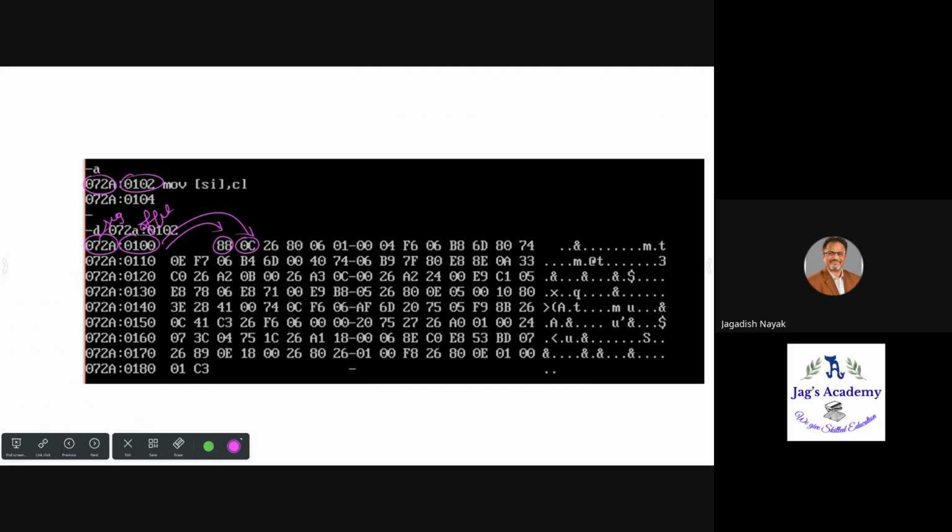Also, in direct and immediate, there's only an 8-bit transfer. We just add the low byte, right? Yes, or the high byte. Always, that part of the number which is there in the instruction, you need to add to the machine instruction. Even for 8-bit, it's just the low byte, no high byte. For 8-bit it is only one byte.